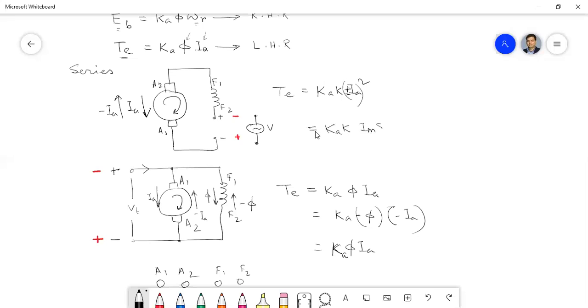No, sir. I think it will rotate with the average value of the sinusoidal voltage because 50 hertz is too high a frequency for the system. Not the mechanical average value, it is the RMS value, because the square is there. So that means the DC series motor will run in alternating supply as well.